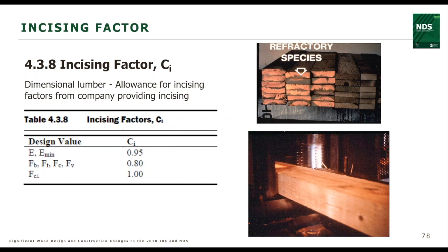These refractory species need to be incised to allow treatment chemicals to penetrate the wood. So when you incise the lumber, it requires the application of an incising factor.